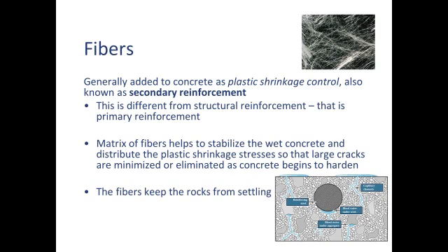In order for it to get there, the more it's squeezed and the more water that has to come out, the bigger the channels it has to form. And those channels don't go away. So those channels form weak spots that can turn into cracks. These big open channels make the concrete very porous. You have trapped water pockets under the rocks that can create voids that can lead to spalling and pop-outs. That bleed water on the surface can alter the water-cement ratio of the surface if that isn't removed or allowed to dry before finishing begins.